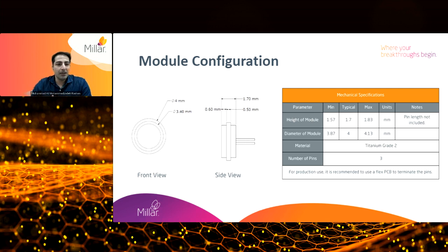For early prototyping, wires can be soldered to the pins, making sure they are not exposed to heat for long periods. However, for long-term scalable use or production applications, we recommend using a flex PCB to interface with the pins, providing better reliability and easier integration.